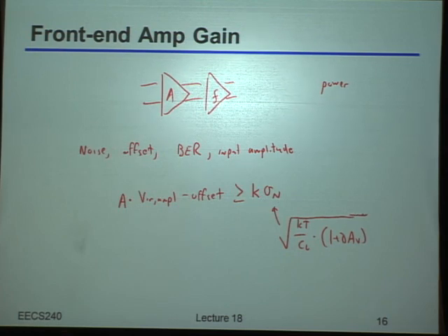Well, plus some more. So what's the other some more? Like 50 divided by our load times A_V squared. Oh, okay. So you're trying to include the self-loading, etc. You're absolutely correct. You should include the self-loading. I'm not going to deal with that for now, but you're absolutely right. There are some self-loading terms and some other stuff that may pop into the picture. Okay. So you said, isn't there also some noise from the termination resistor? Absolutely correct. You should include that as well.